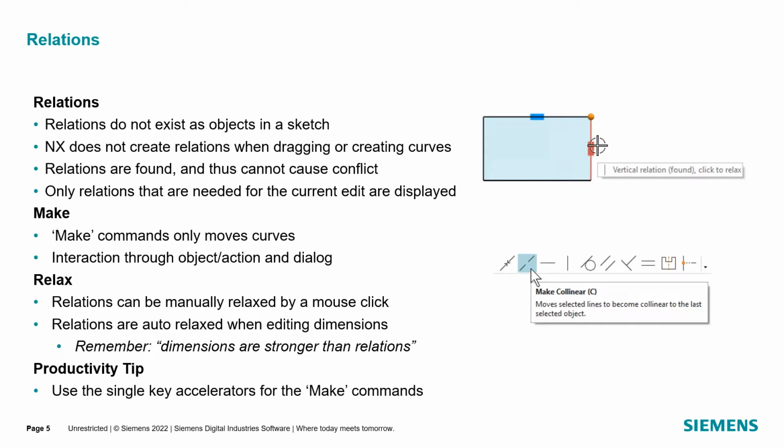But the big tip to remember here is dimensions are stronger than relations. That's one thing as we've been going around doing this. A little background, I've been involved with the sketch since before it was released, going way back to when we first started doing usability studies with customers and colleges and a whole bunch of stuff. So I'm well versed in what areas people need a little bit of reminder, and that's the biggest thing we try to remember all the time now: dimensions are stronger than relations. If you change a dimension, it will break some relations that it found to make that change if needed.